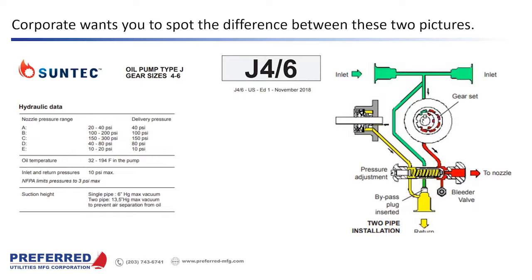You're much better off doing a low pressure loop. If it's a mechanical atomized job, you're much better doing a low pressure boiler loop than you are using day tanks. There's absolutely no reason to use day tanks on a boiler job.